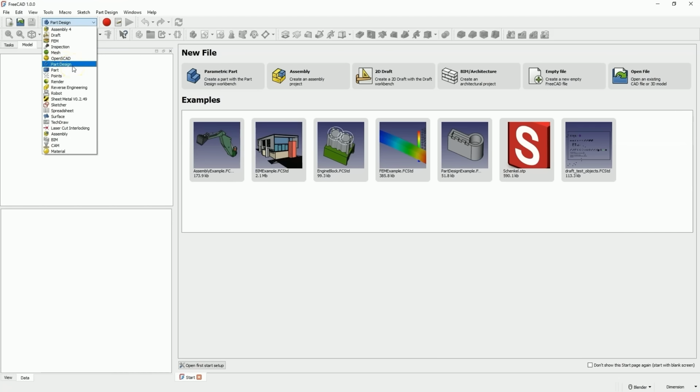There is also a Part workbench where we can create 3D models, but it is the Part Design workbench that is primarily used for creating parts. The work methodology used in this module is similar to other 3D CAD systems. In this module, we work on features and parameters, meaning we create a parametric model. This model is usually created in such a way that we first create a 2D sketch and then use 3D solid creation operations based on the 2D sketch to create a 3D solid.